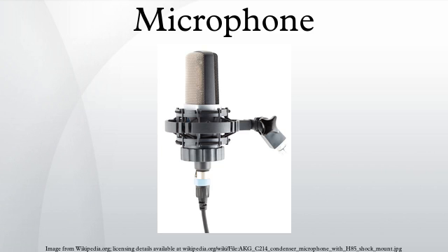Capsule design and directivity. The inner elements of a microphone are the primary source of differences in directivity. A pressure microphone uses a diaphragm between a fixed internal volume of air and the environment, and responds uniformly to pressure from all directions, so it is said to be omnidirectional. A pressure gradient microphone uses a diaphragm that is at least partially open on both sides. The pressure difference between the two sides produces its directional characteristics.